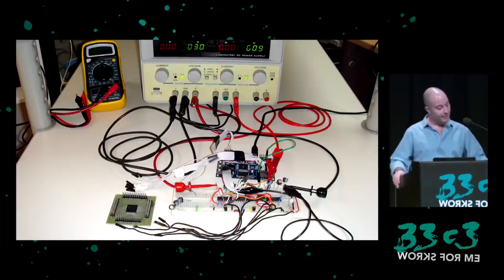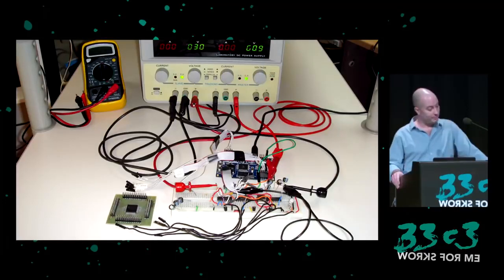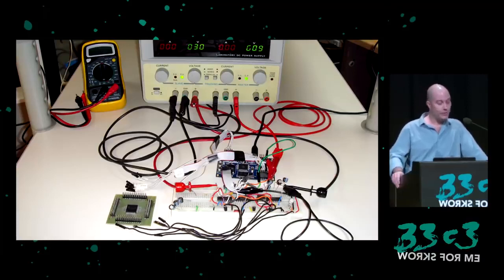To be able to learn more about the ACP, I started to look at glitching the chip. If I can succeed to glitch the chip, I may be able to find a way to read and even write memory, and possibly a way to run my own software directly on the chip. This would allow me to control the hardware peripherals and be able to observe the chip's operation under different conditions.